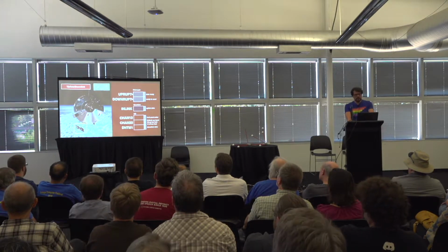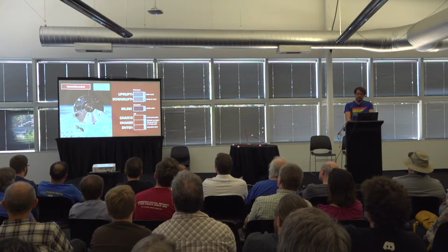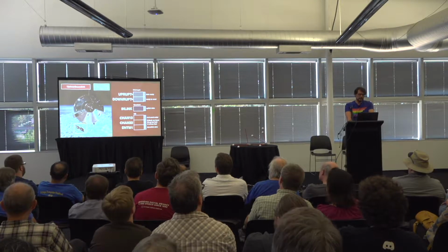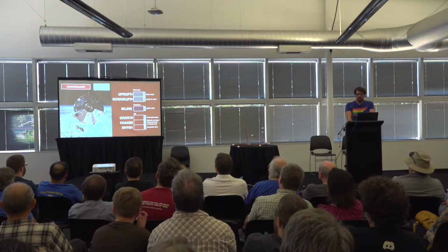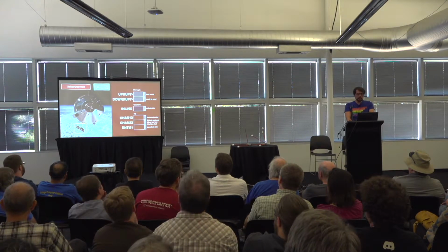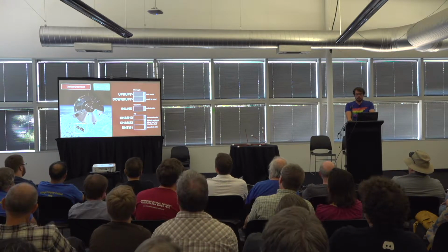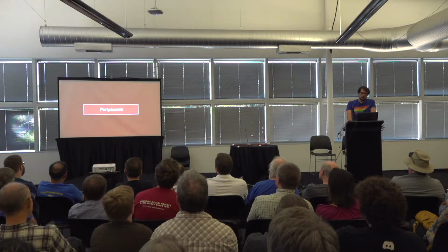There's bidirectional digital radio communication, S-band, between mission control and each spacecraft at a selectable speed of 1.9 or 51 kilobits per second. Data words from mission control are shifted into the in-link counter and trigger interrupt UPRUPT. Data words to be sent are stored to the I/O channel DNTM1, and the DOWNRUPT interrupt will signal a program when it can load the register with the next word. These were some of the interesting peripherals.